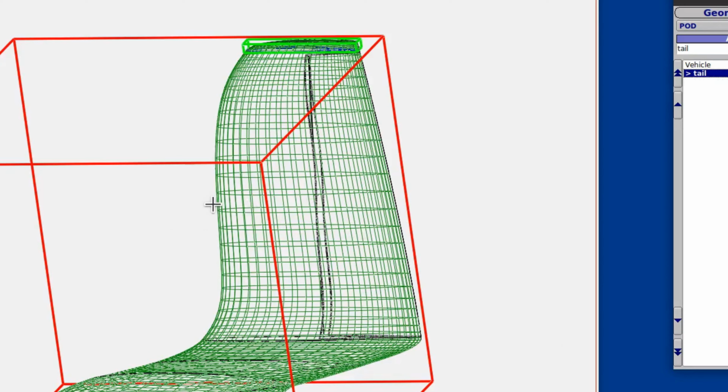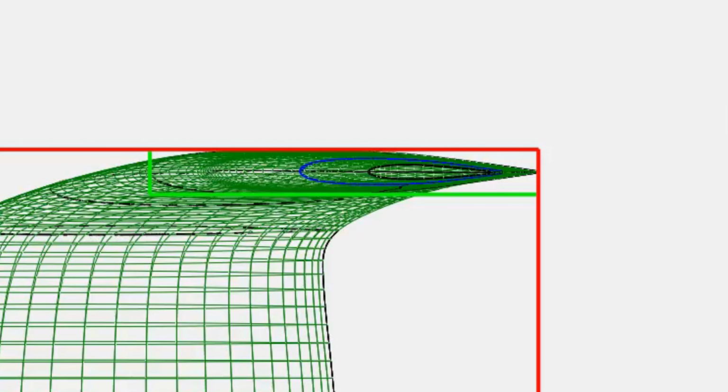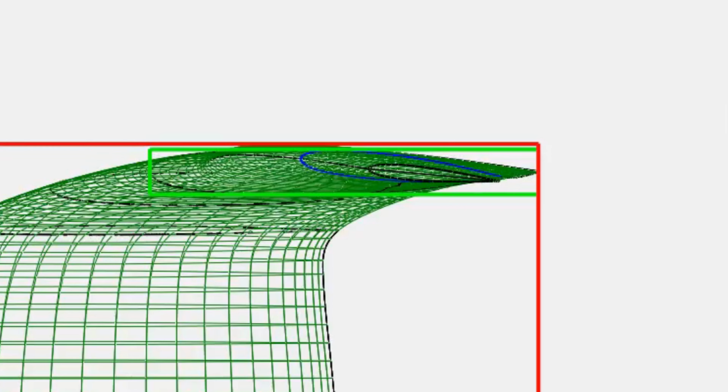We need to know the chord load distribution also. This will help us figure out the shear load on the skins of our vertical tail, the horizontal stabilizer, and the rudder because of twist that occurs. Typically, when you have a chord load, you're going to have more load at the leading edge and less load at the trailing edge. Now, let's say that load is into the screen, going in like this. That will cause this leading edge to start pushing in the same direction as that load. And as you go along the span, that twist is going to get greater and greater.